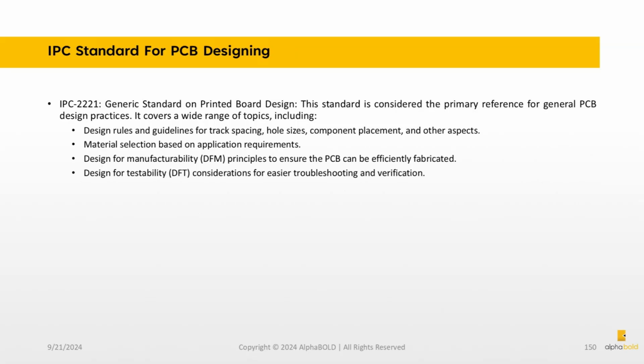IPC 2221, Generic Standard on Printed Board Design. This standard is considered the primary reference for general PCB design practices. It covers a wide range of topics, including design rules and guidelines for track spacing, hole sizes, component placement, and other aspects. Material selection based on application requirements.